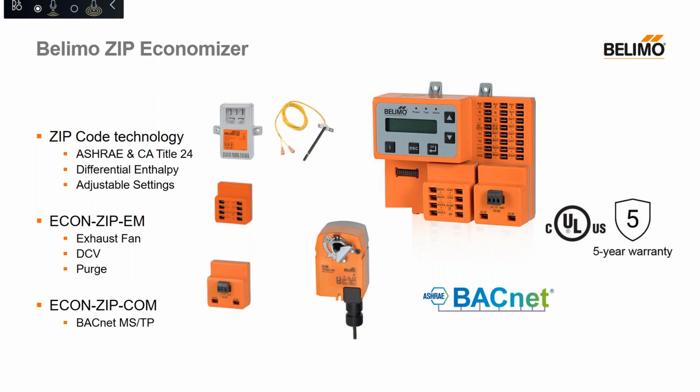There are 75 objects within the Zip. A function that can be displayed in your BMS through BACnet is alarms. One of the over 30 alarms in the Zip is if a sensor is out of range or not detected, giving a solution to verifying your components. If you do not have BACnet MSTP, the alarm contact can be used for a remote pilot light to notify people in the space.